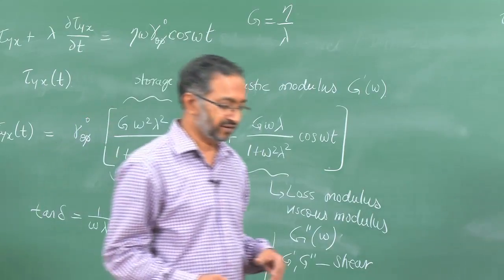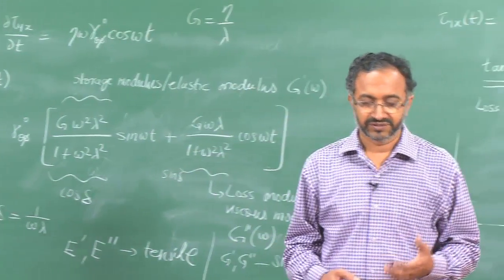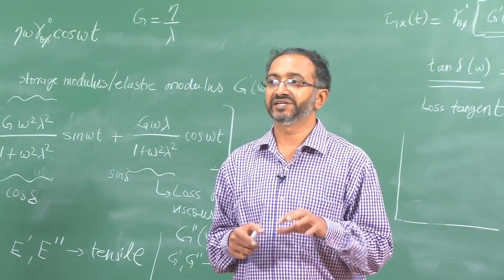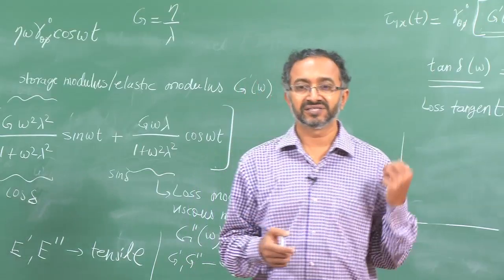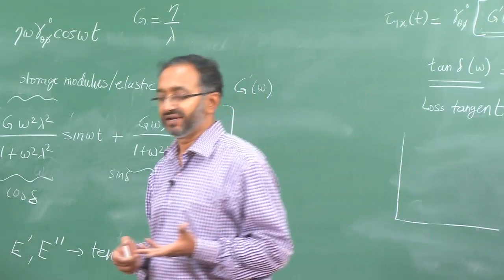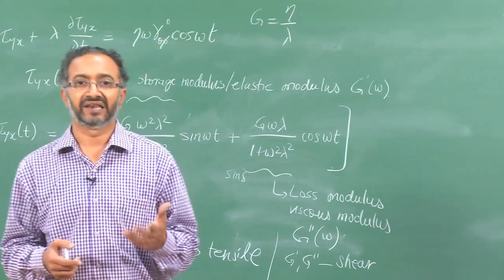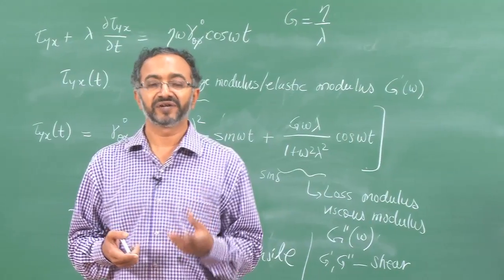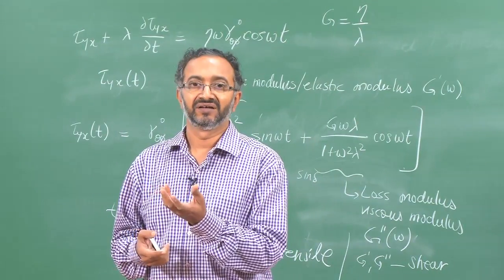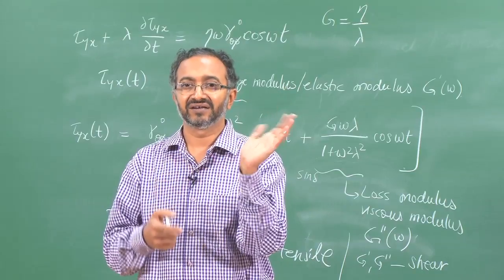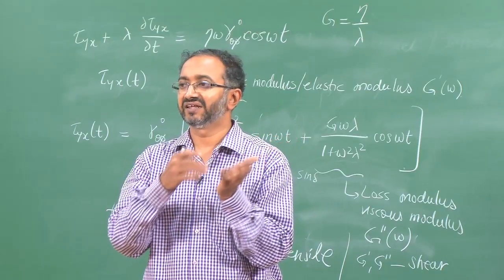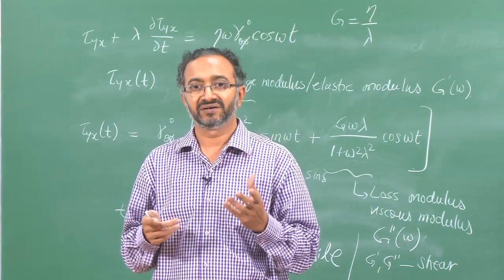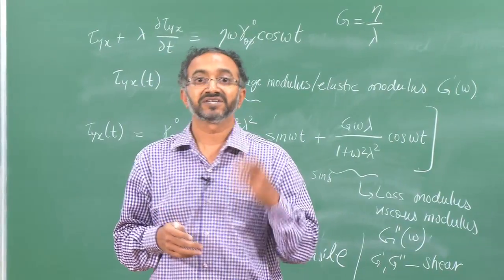For example, when we are doing a steady shear experiment, we vary the strain rate, right, and therefore viscosity is a function of strain rate. So, in this case what we vary is frequency, and in general let us say we are developing a gel for cold cream applications. Then we would like to know how it would respond at low frequencies, because that is when it will be in the bottle, or when I take it out on the hand it will remain almost stationary. So, with little shear how does it respond, but then when I start spreading it or rubbing it, it is very short time scales, which means high frequency.